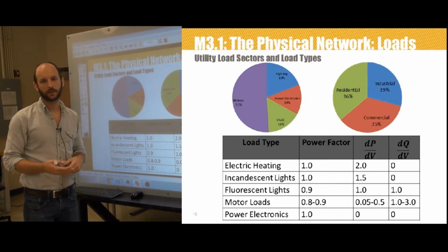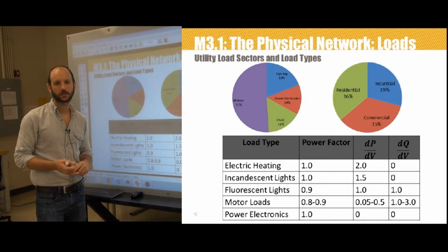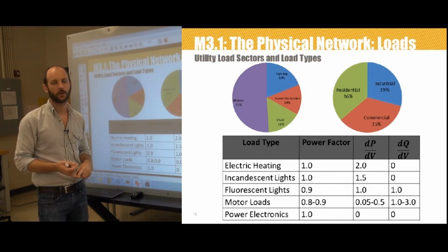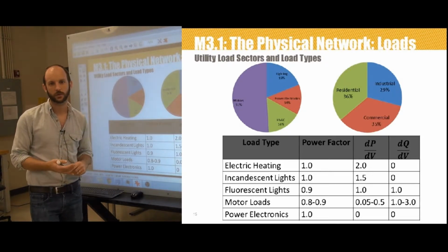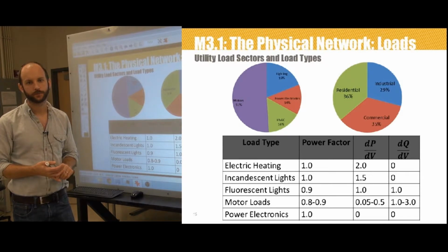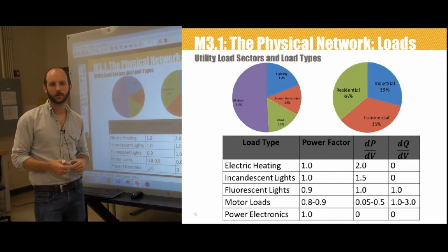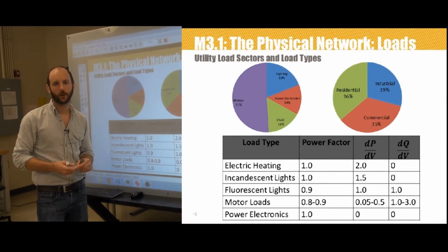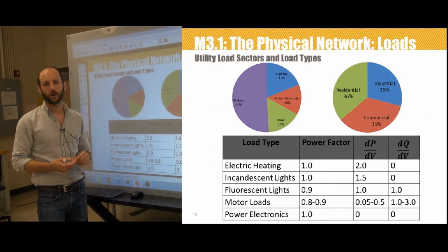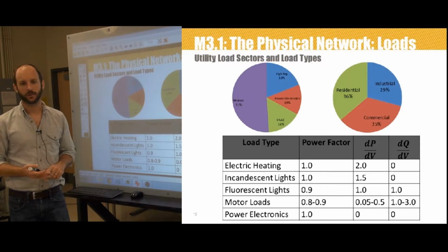Since the frequency of the power system is typically fixed at 60 Hertz, of most interest is the voltage sensitivity of the load, which is often used by utilities to aid in system analysis of power flow, and what we'll later discuss is called stability of the system. When performing these analyses, utilities will estimate the mixture of loads on their systems, and then build up an aggregate model of the load behavior using a combination of constant impedance, constant power, and constant current representations.